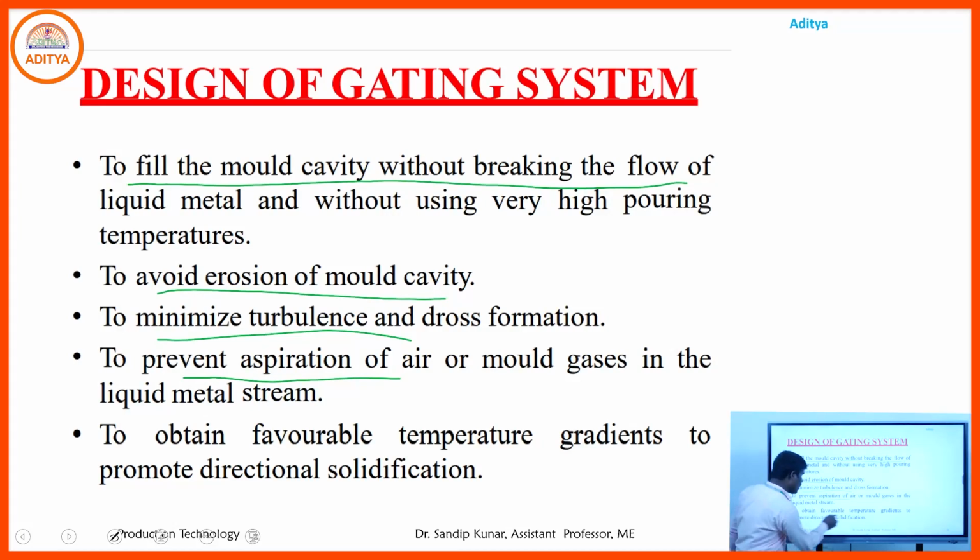Okay. Another, to obtain a favorable temperature, always maintain the pouring temperature so as to fill up the total mold cavity. Otherwise, it does not fill up the total mold cavity shape. So cold shut, that type of defect will be generated in the casting product.